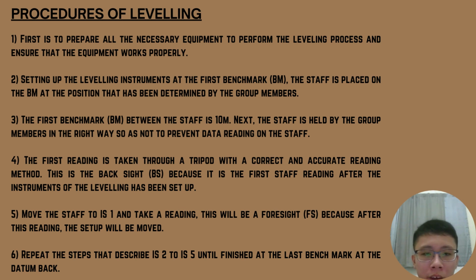Next, the staff is held by the group members in the right way so as not to prevent data reading on the staff. The first reading is taken through a tripod with a correct and accurate reading method. This is the backside BS because it is the first staff reading after the instruments of the leveling has been set up.